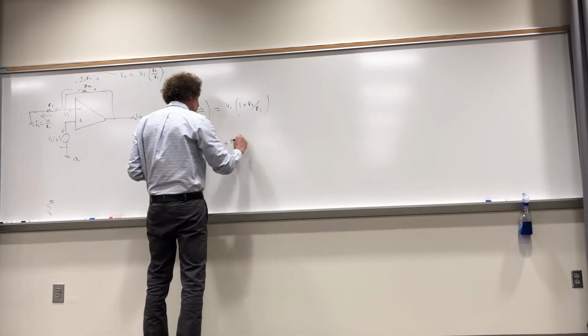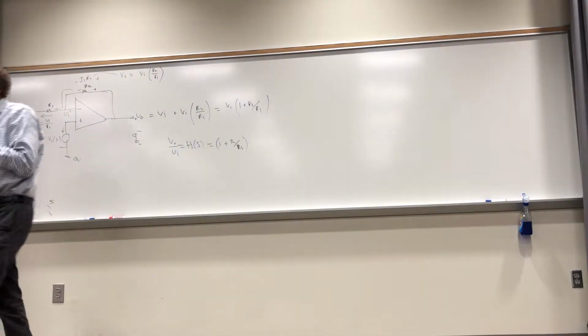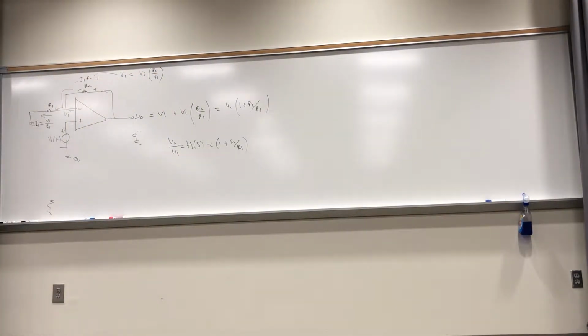Here, there is no inversion at all. And you can choose the values of R1 and R2 in 1 plus R2 over R1 to give you any gain you want. You follow me, class? That's a non-inverting amplifier. That's not as common. Most of the time they feed the signal through the negative terminal, and that comes later, and I can't get into that here.